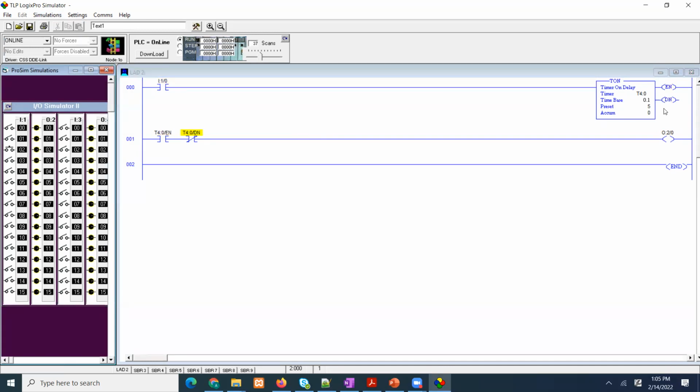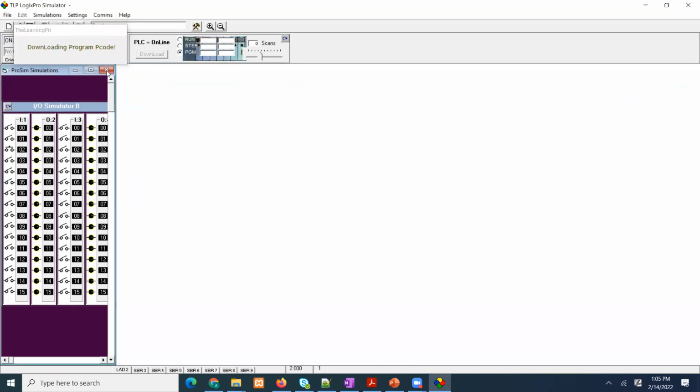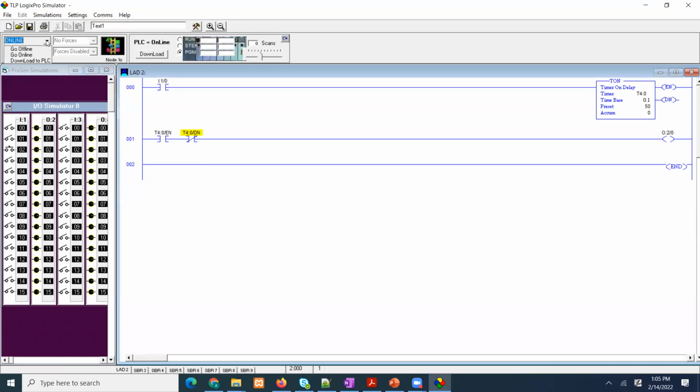So let's change that to 50. Sorry, it did not get changed to 50. Say PGM, change it to 50. Let's download it. And we're online. Here we go. Let's close this switch again. And you guys see this guy is on right away, yes? And after 5 seconds, he is done, yeah?